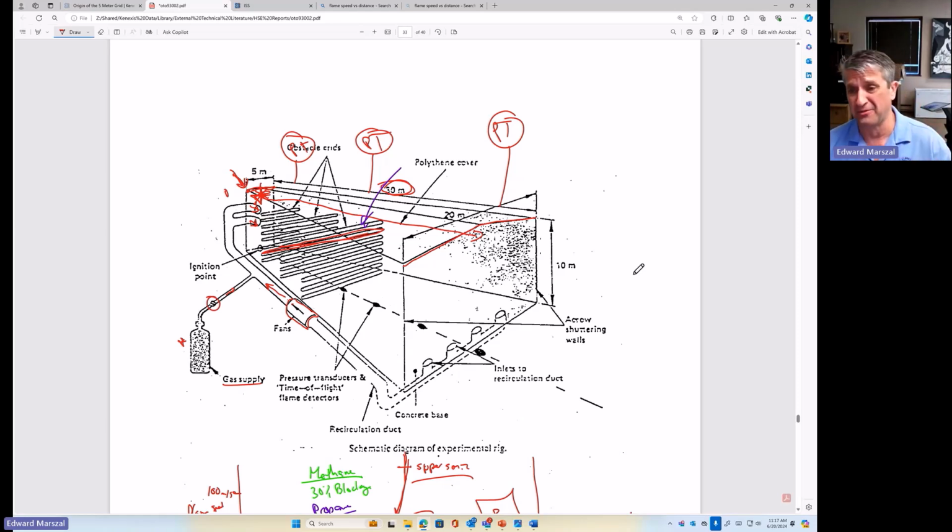You should be using computational fluid dynamics and toss all this other stuff out the window. So the size of the critical gas cloud is a function of what material you released, what is the degree of confinement of that material, and we're still going to assume you're going to get a relatively weak source of ignition as opposed to a very strong source of ignition when you're making that decision.